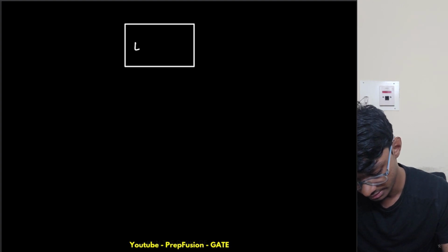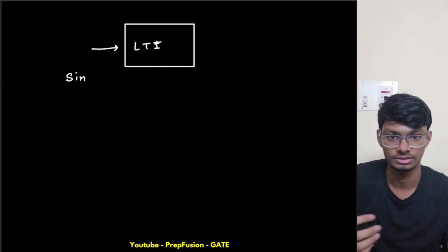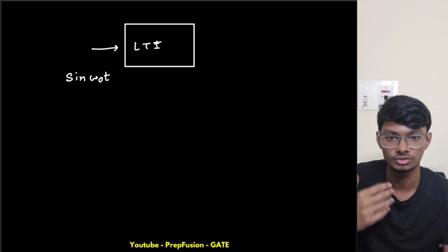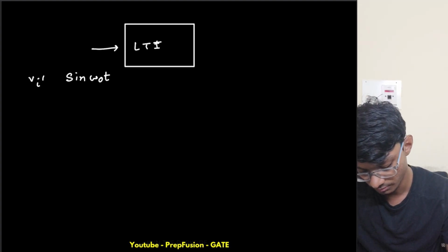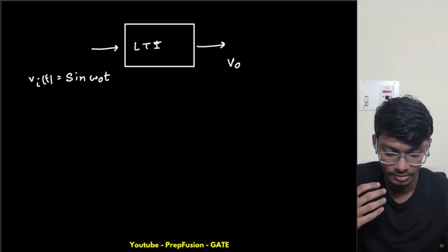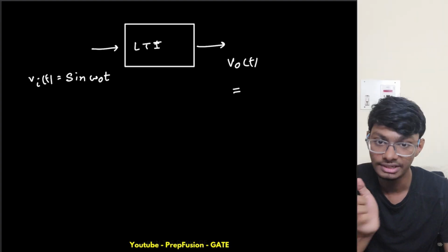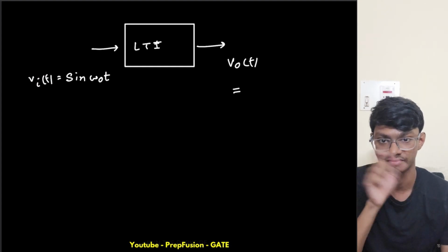If I have one LTI system, and if I give it a sine function or a cos function, a sinusoid waveform, as an input, what will my output look like? My output will simply be a scaled version of this sinusoid in magnitude and also in phase.